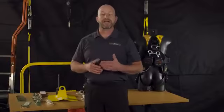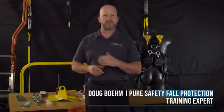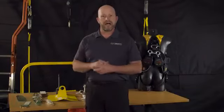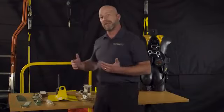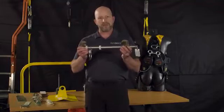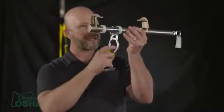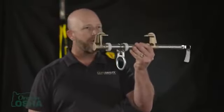There are many of us that work inside or in other environments where we don't have a walking surface such as a roof or a substrate such as that. Take an iron worker or something similar to that, where we have an exposed I-beam. Another common tool is a beam clamp or a beamer clamp that is designed to attach around multiple flanges merely by squeezing that trigger and getting it around one side of the I-beam flange, bringing it up like that, and then you will just slide it in, connect, and then we would hang our retractable or put our lanyard to that, and then it would be suspended from the I-beam.